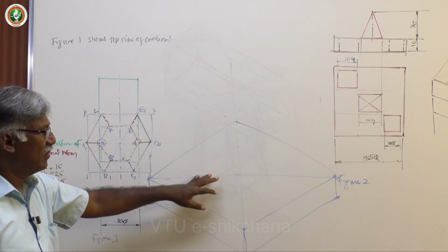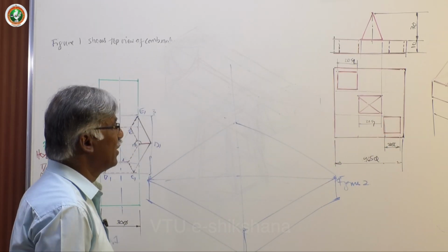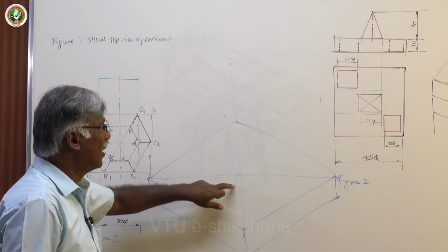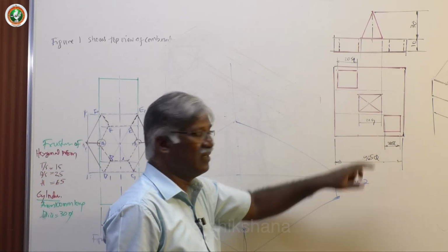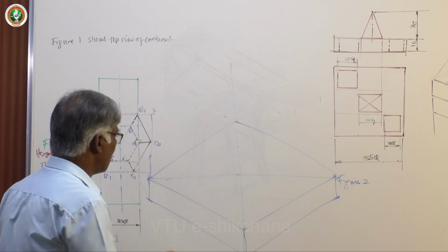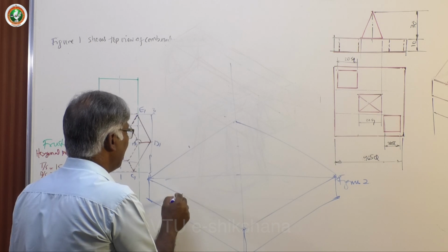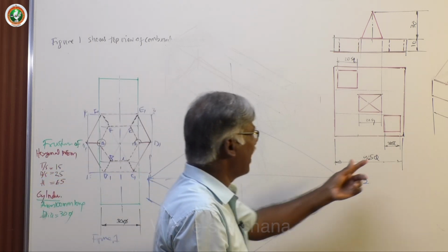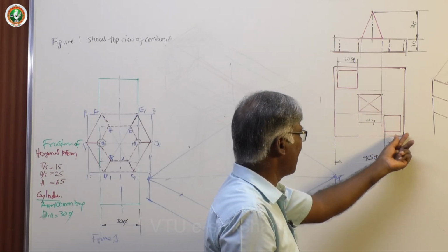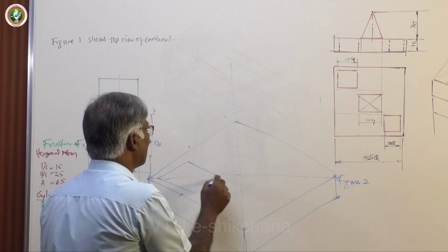So this completes the base solid. We don't have the complete base solid, I have 2 holes. I can complete the pyramid easily, we will do it afterwards. First, let us do these holes. Again, that is easier. Measure 20, 20, and he has given some gap. See, total is 90, 60, 60, 60. In between, some gap is there. After leaving that, draw this square. That's all.